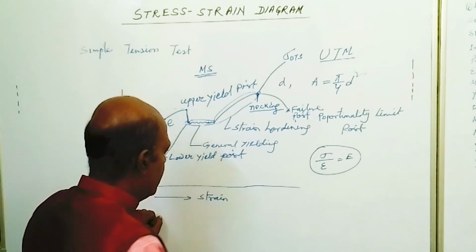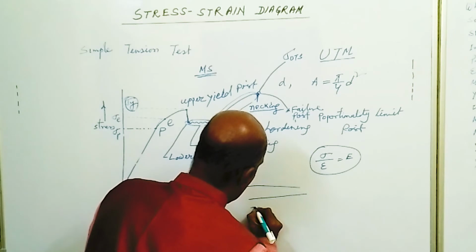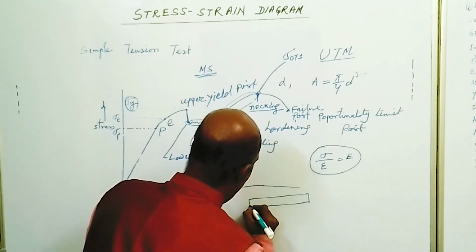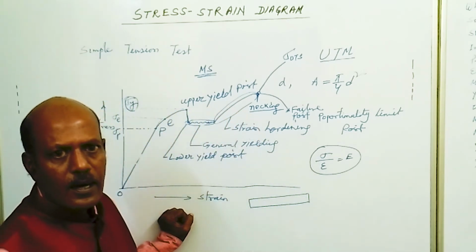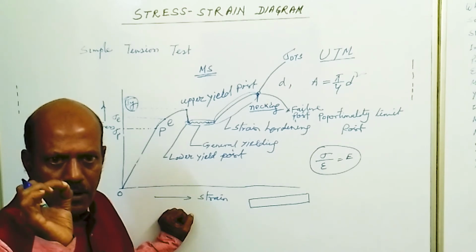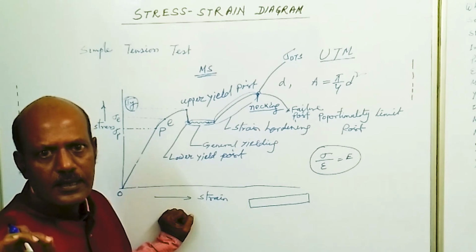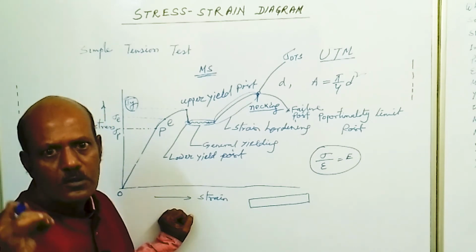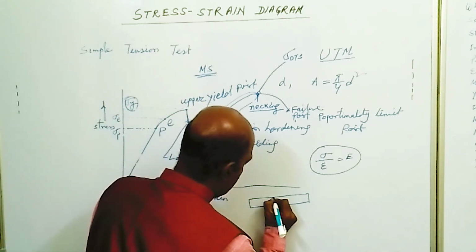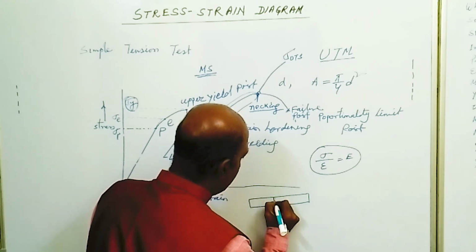What is necking? As per our assumptions the body is a slender bar, that means all the cross sections of the bar between the gauge length are of equal size. Theoretically that may be possible, but practically it is not. So some area may be slightly less than the surrounding area.